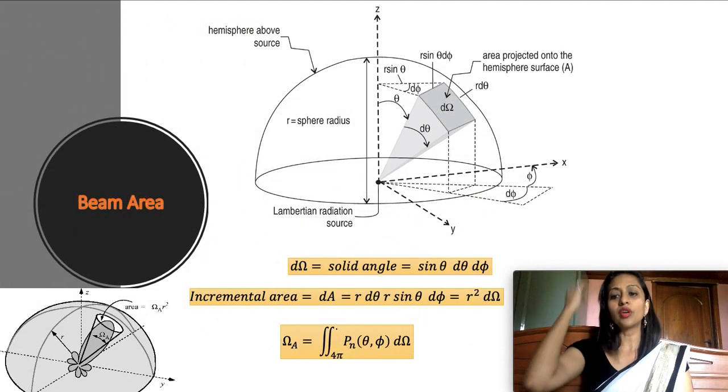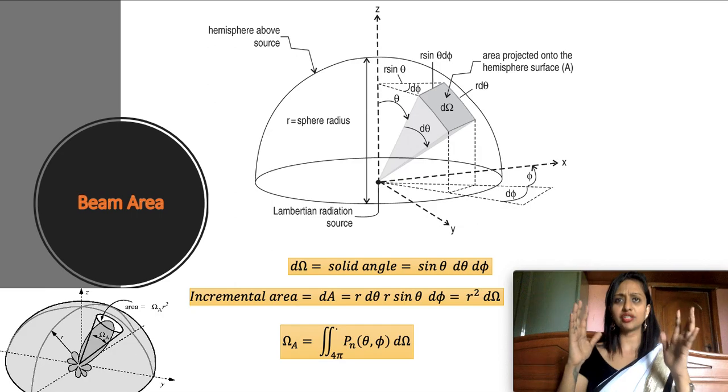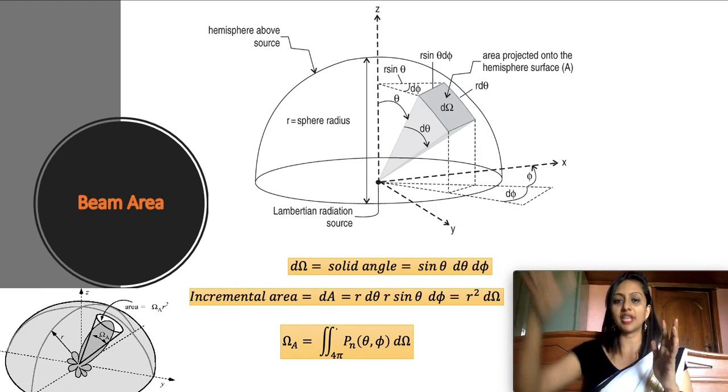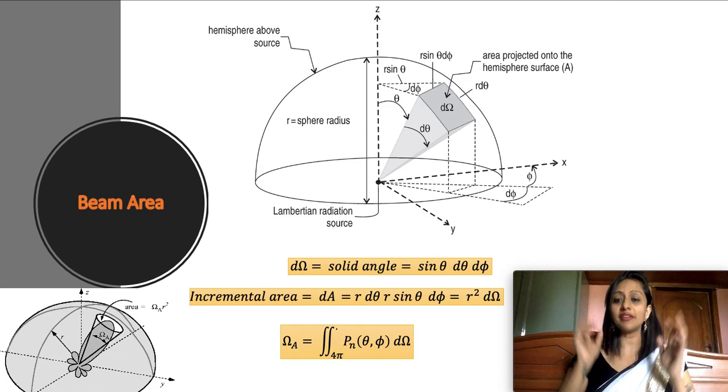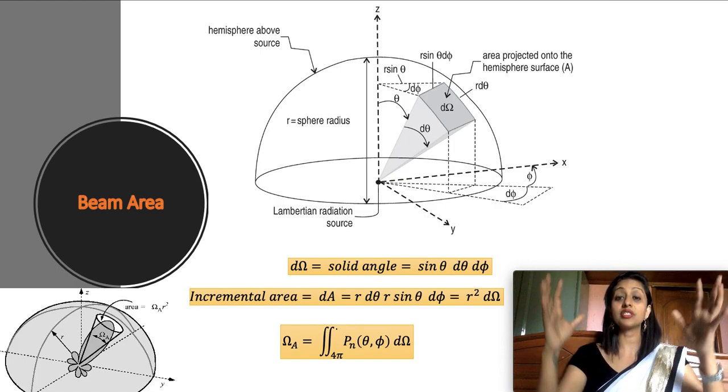Okay, having known what the radiation pattern and the polarization are, the next term that comes into the picture is beam area. Okay, so now radiation is put out, right? Directional or omnidirectional, we'll come back to it. For a directional one, there is some coverage happening in one particular direction. Now I need to know how much is the area which is covered. Distance and everything comes one by one now. So I need to know how much my antenna has covered, what is the area covered.